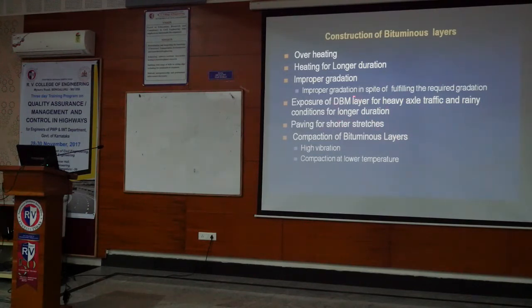Paving for shorter stretches should be avoided, and in no case should we put high vibration on the bituminous layer. It's dangerous. After all, for a 40 or 50 mm layer the paver itself does the job.